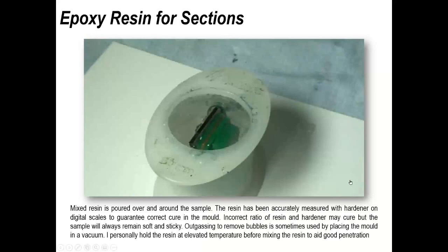If it's a switch, if it's some sort of inductor, if you could take away whatever material, or if it's a switch, you might fill the switch as well. The reason being, you're not left with a cavity which is going to collect resin, it's going to collect other contaminants that you're going to produce during the microsectioning technique. So again, it's preparing for issues that might occur.